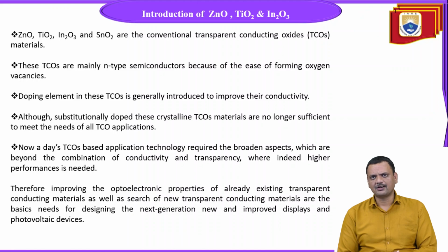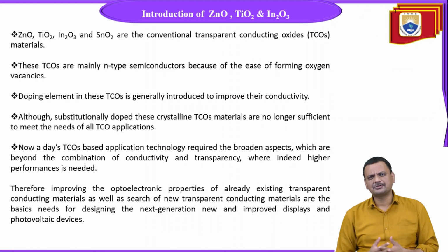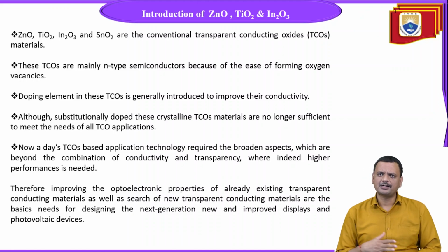All are metal oxides. Among all these, indium oxide has some remarkable properties regarding optoelectronic behavior. Why? Because once it is doped with tin, it shows higher conductivity, comparable to metals, and it also shows transparent behavior.